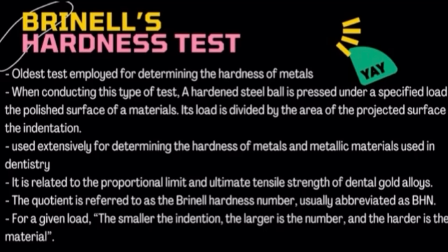It is also related to the proportional limit and ultimate tensile strength of dental gold alloys. The quotient is referred to as the Brinell hardness number, which is usually abbreviated as BHN. For a given load, the smaller the indentation, the larger is the number, and the harder is the material.